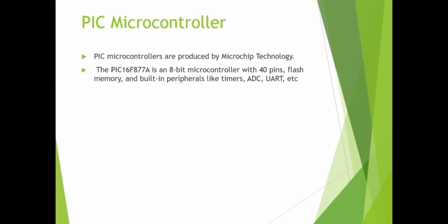Our chosen controller PIC16F877A has an 8-bit processor, 40 pins with lots of input output, built-in analog to digital converter, timer and interrupts, support for USART, SPI and I2C.